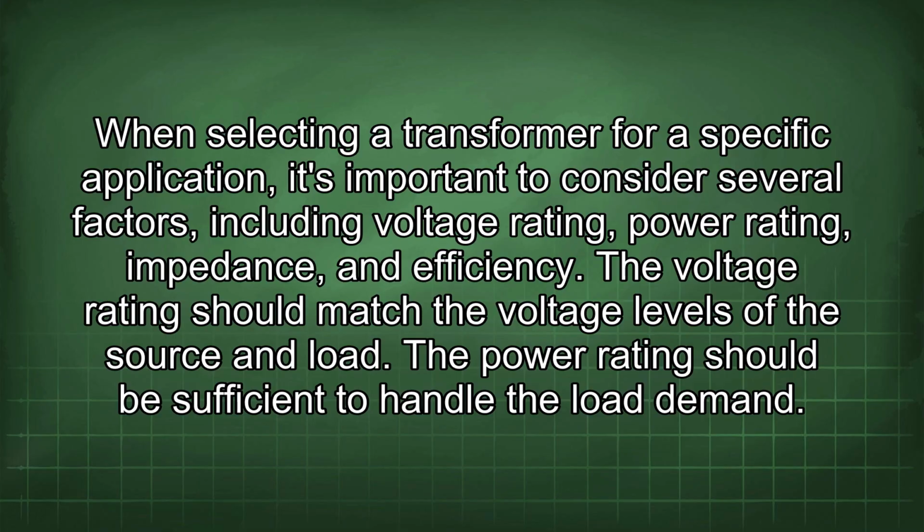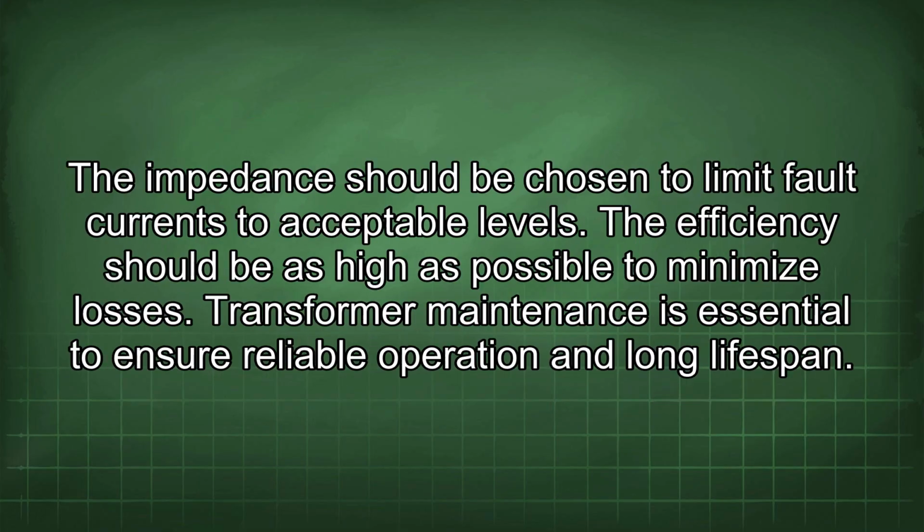When selecting a transformer for a specific application, it's important to consider several factors, including voltage rating, power rating, impedance, and efficiency. The voltage rating should match the voltage levels of the source and load. The power rating should be sufficient to handle the load demand. The impedance should be chosen to limit fault currents to acceptable levels. The efficiency should be as high as possible to minimize losses.